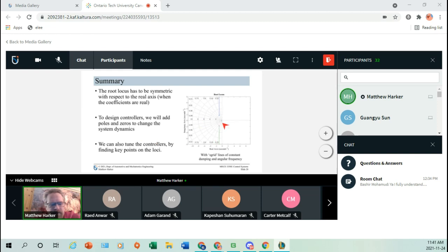This sgrid is really only valid for a second order system, right? So these complex conjugate poles. But what we'll generally assume when designing controllers is that we have one or two dominant poles, right? So we might have a system with poles over here and poles over there as well, but these are going to be the main influence on the response, in that idea of having dominant poles. Okay, are there any questions about those examples?